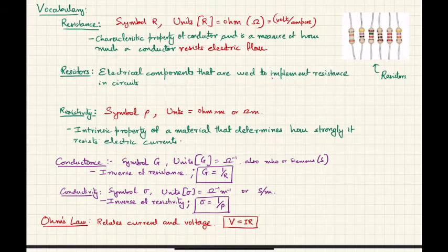And how is it different from resistance? You should ask, how is this different? Well, resistivity only depends on the material. Resistance depends not only on the material, but also on the dimensions of the material, that is how thick a wire is or how long a wire is. And so we will talk about that briefly as well, the link between resistivity and resistance. Already from the units itself, you can see that there must be some kind of link. The meter there means that, again, we're talking about the dimensions of the material.